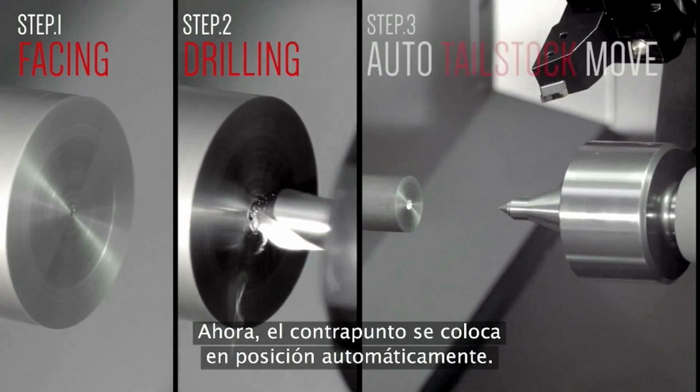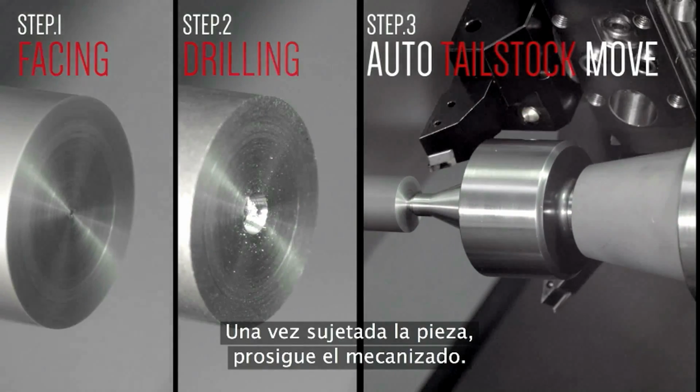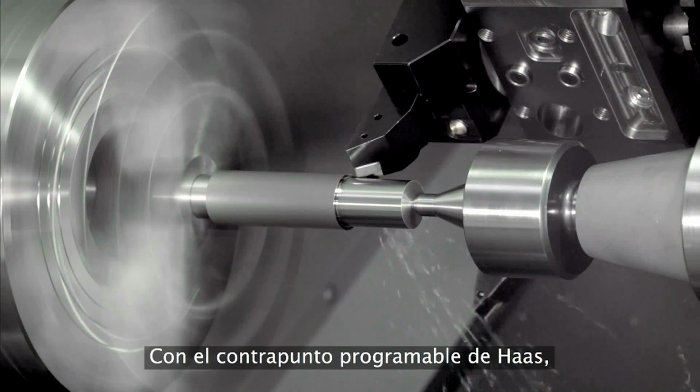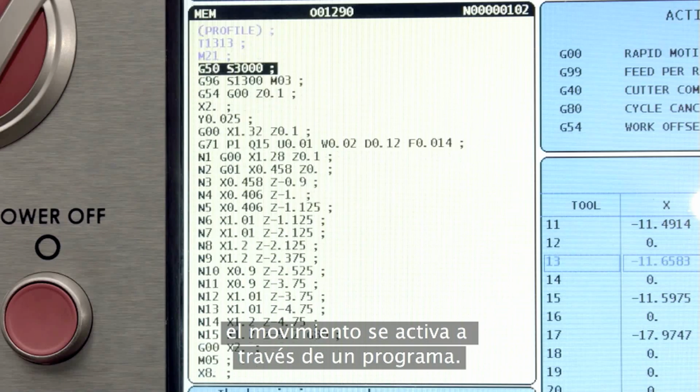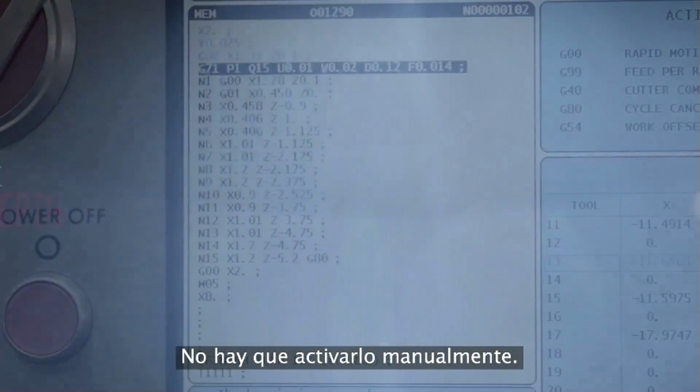Next, the tailstock moves automatically into position. With the part supported, the cutting continues. Using the Haas programmable tailstock, motion is initiated from within a program. No manual activation is needed.